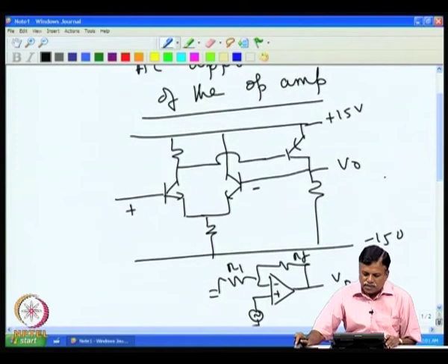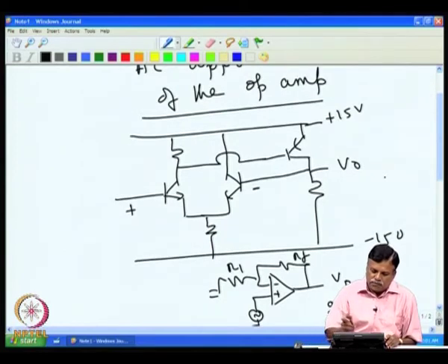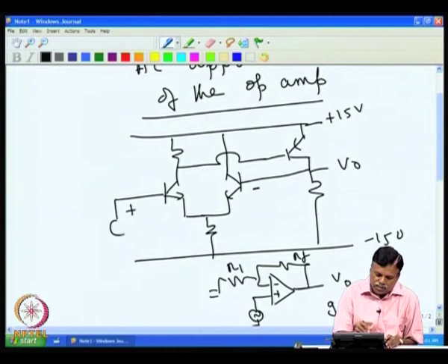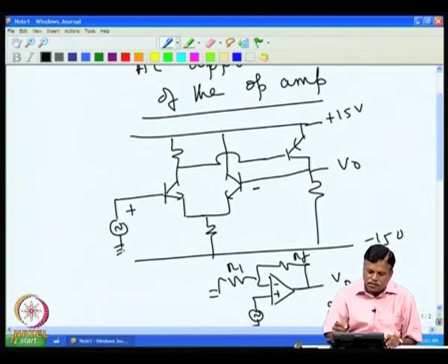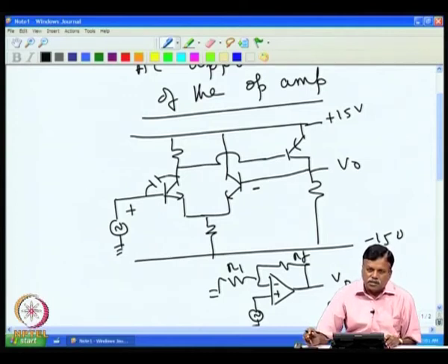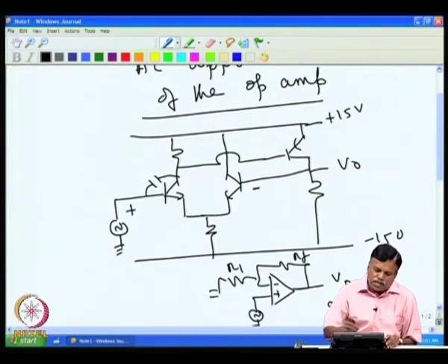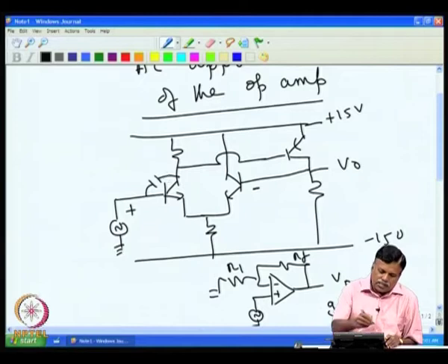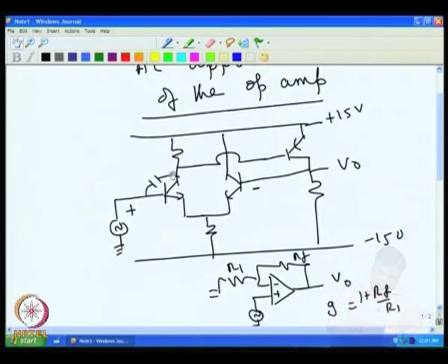For that, we go back to our operation amplifier circuit. Now, in this case, if I am trying to amplify AC voltage, for example, I apply AC voltage here and trying to get amplified AC output, then we have issues mainly due to the capacitance between this, called Miller effect capacitance. Actually, this capacitor is coming due to the diffusion charges, because charge that is diffusing takes its own time. So, that is represented as an equivalent capacitance here. This is the famous Miller effect capacitance, and similarly we have capacitance here at the input.